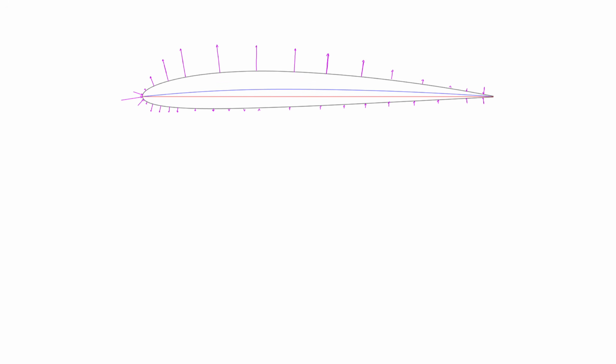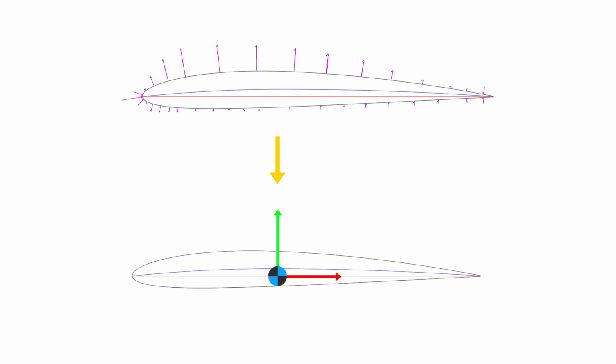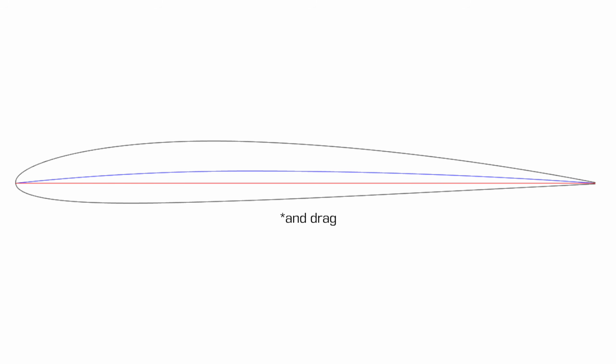During aircraft design, it is useful to express the lift and drag forces that an airfoil generates as if they are resulting at a single point along the airfoil's chord, as shown earlier. To determine where that point is, we first need to review the pitching moment. In addition to lift, airfoils will also generate a pitching moment, where a moment is a torque that is created by a force acting at a distance from some point.